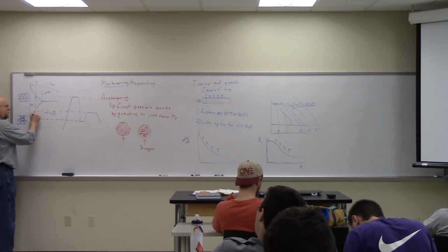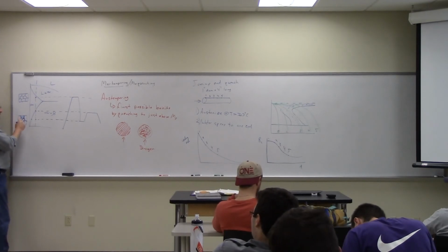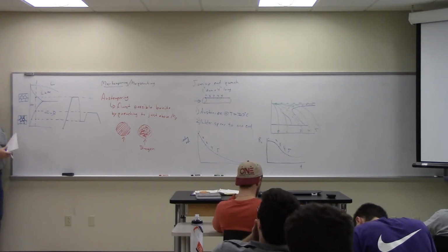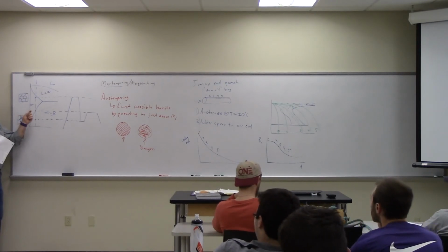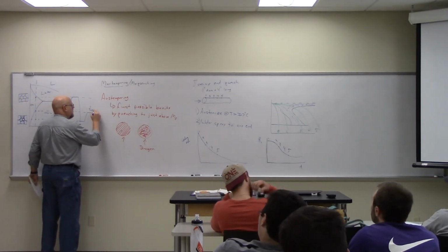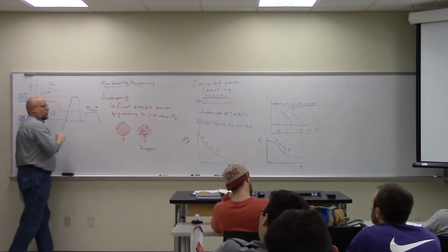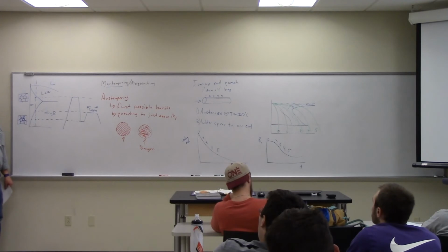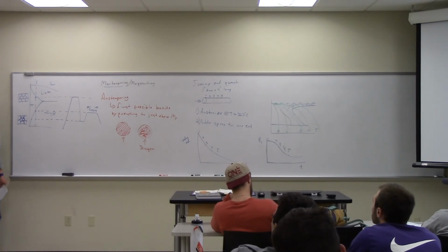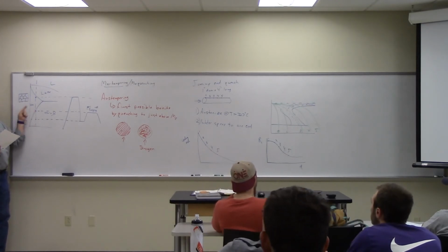Right? Because the alpha that's here has this concentration of B material. When I get right up here, just below that, now all the beta at the grain boundary is just going to be reabsorbed back into the grain, so I have just the alpha grain and just a little bit of driving force to form beta. But I stay there a long time. Right, this time here, I stay there for a long aging time. T sub aging, aging time. Okay? Subscript. So I stay there for a long aging time. What's going to happen is that I'm still just below it, so the beta wants to come out.